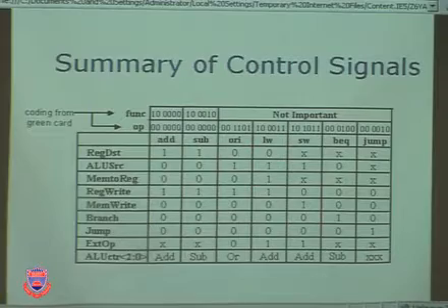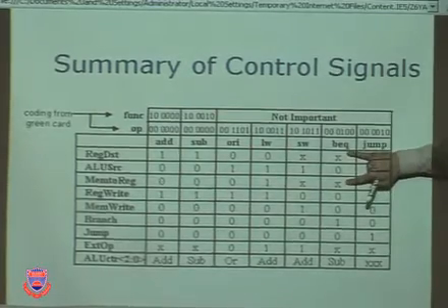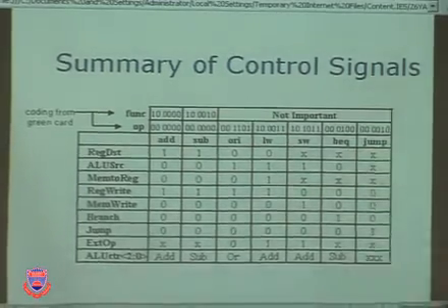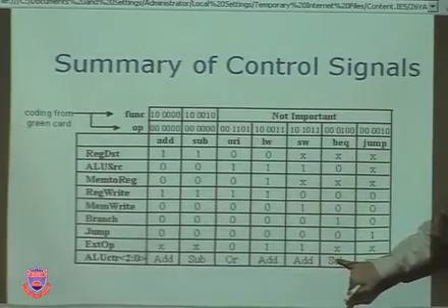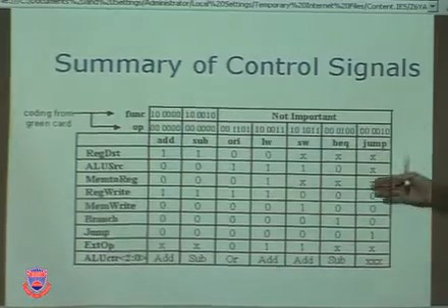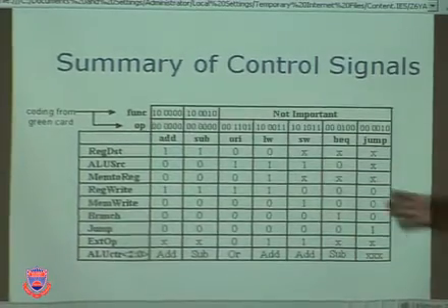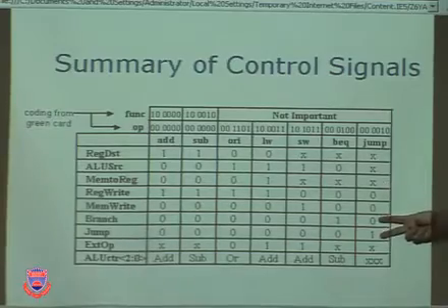Yeah. So if you want to do a BEQ, we don't care about that one, we don't care about that one, we don't care about that one. But some of them have to be 1s and 0s, and you're sure that you need to subtract in the ALU, right? But for a jump, we don't even care what we do in the ALU. We don't use it. Lots more don't cares. Just make sure you please don't write anything. Yeah, in those 2. And this is the branch and jump.